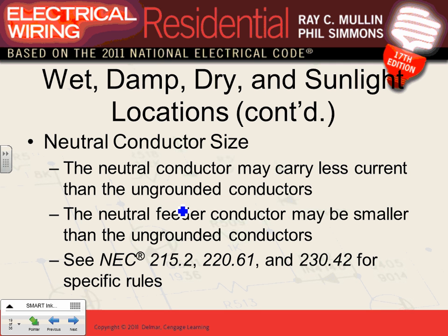So just FYI, neutral sizes, I promise you we're going to do a lot of calculation based on sizing the neutral. There are a couple of things about neutral sizes, not for branch circuits, but for feeders. Neutral sizes for feeders, guys. The code says if you have a feeder, now we're talking about feeders, we'll do that in commercial, industrial. You have to understand that the neutral of a three-phase system always carries the unbalance between the phases. If your system is heavily harmonic, like electronics, the whole derating business is out of the picture.